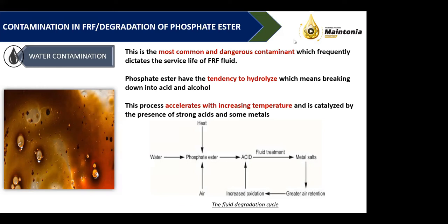Those micro pittings are due to this acid formation. And sometimes we see a silting effect on the spool corners. That is because of high moisture content and mechanical impurity. Combined together, they form the silt.